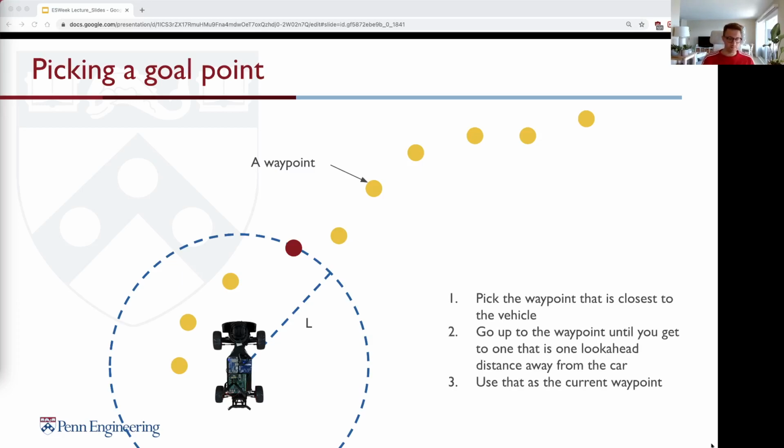That's something we can do. We can also say we choose the waypoint that is closest in look-ahead distance. Like when we make the turning radius and say, hey, here's the look-ahead distance, we have a point that is very, very close to that. And now let's use this one here and try to follow it.